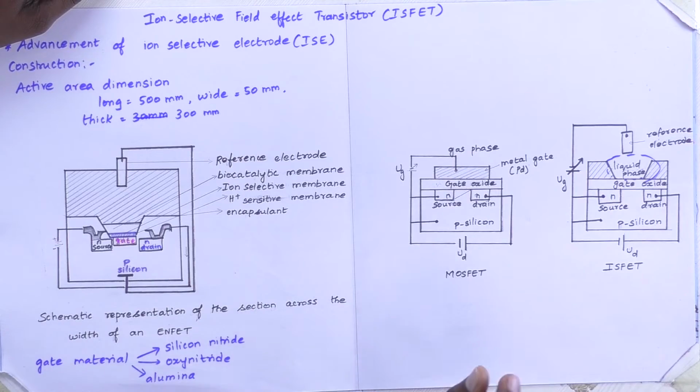This metal oxide FET not only detects hydrogen gas, it also detects ammonia, amine, hydrogen sulfide, and many other gases. Why should we prefer this field effect transistor? Because its size is small and it is cheap and mass produced, as it is fabricated using integrated circuit technology.